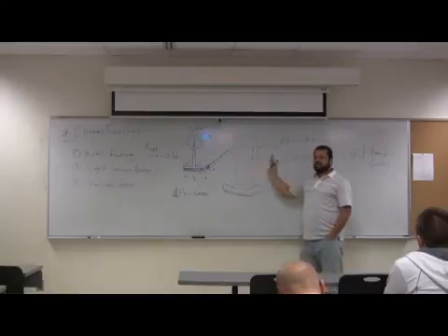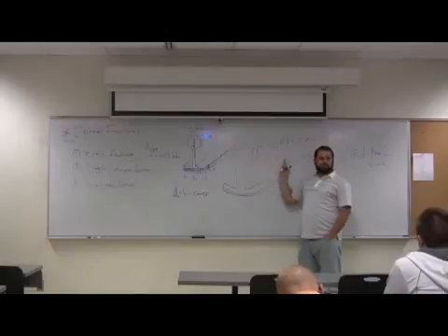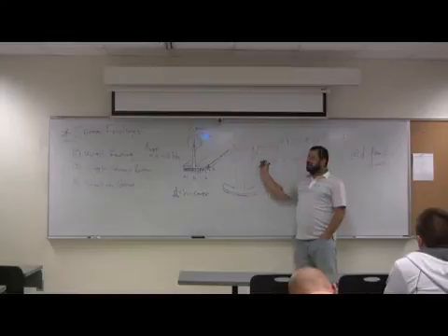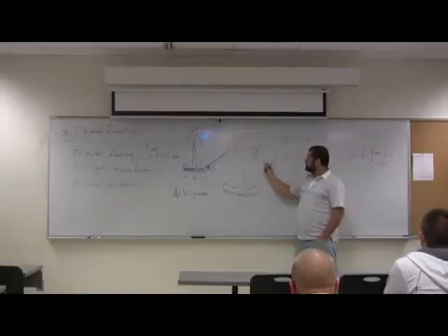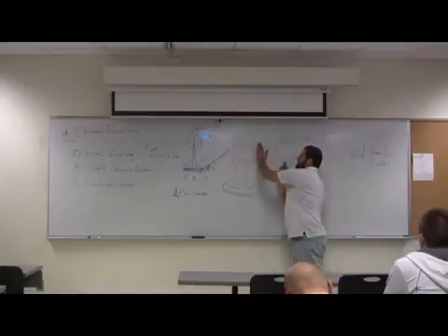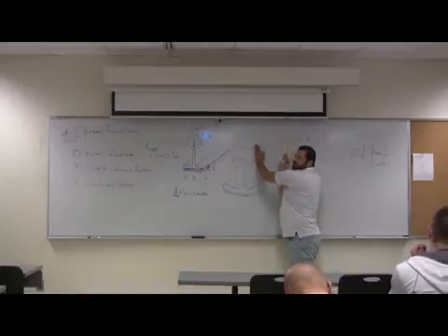So it's like the footing is a cantilever from the face of the wall. This is the cantilever beam now, and likewise from here, so we design one. This is like fixed here. Why? Because this area is confined with the compression coming from here. So this is like fixed here, and this is a cantilever going up.